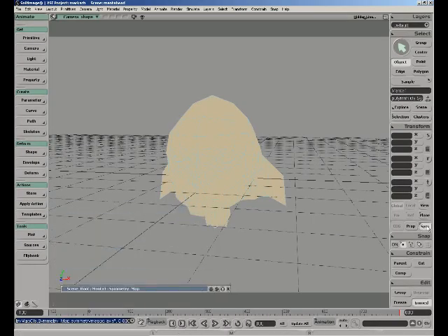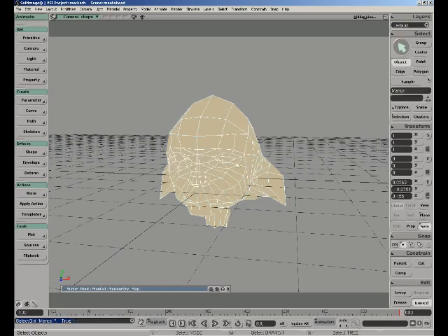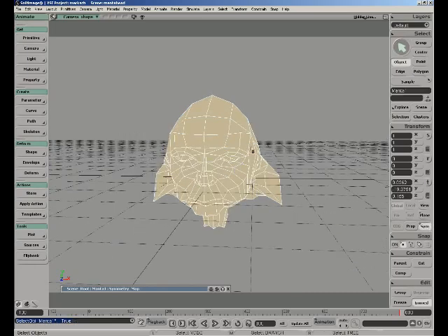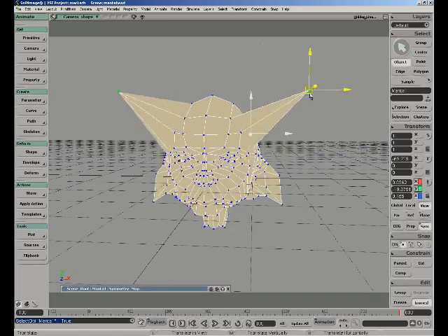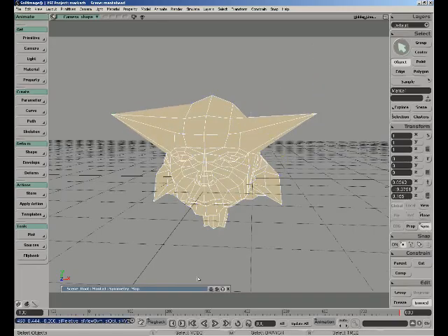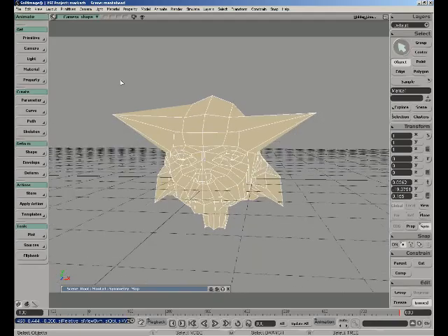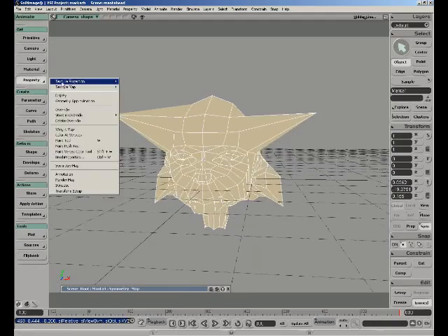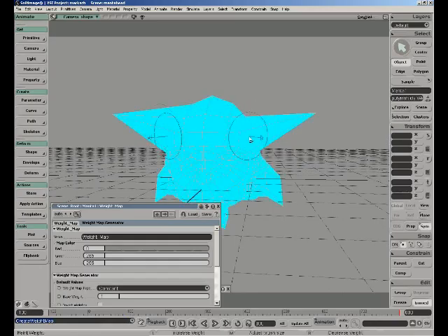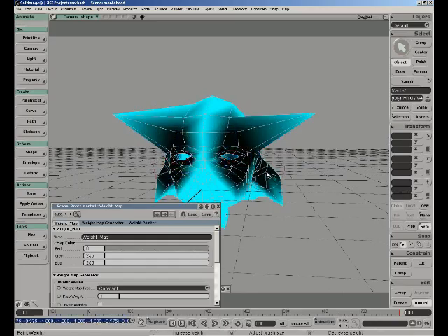Now make sure this button here is checked. If that's not checked, it won't work. But with that button checked and the symmetry map in place, you can then go ahead and model symmetrically. You can go in that pull down and change the symmetry plane if you'd like. We can also, if we apply a weight map to this, show you that your envelope painting tools, all your weight painting tools, everything also works symmetrically as well. So even, again, envelope weights.